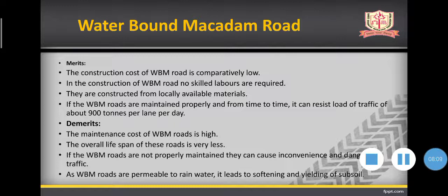So we don't require any skilled laborers. They are constructed from locally available material. Obviously, whichever material is locally available, that is coarse aggregate, fine aggregate, or soil. Now, by using this material, we are going to construct this waterborne macadam road.